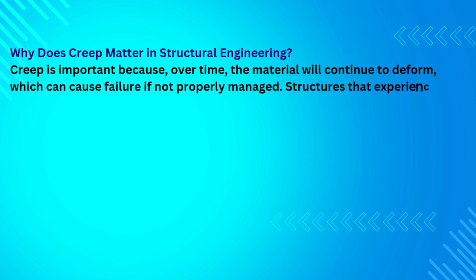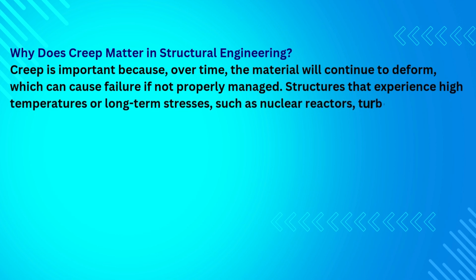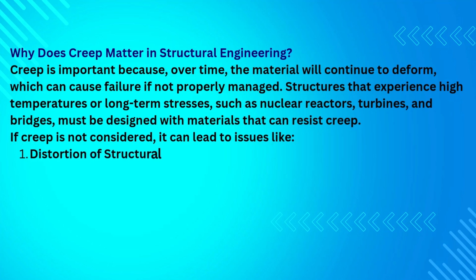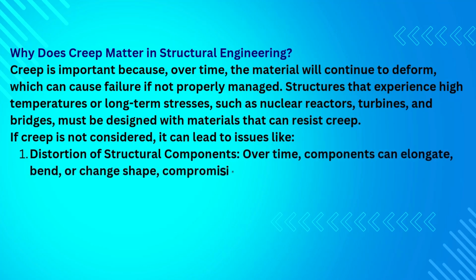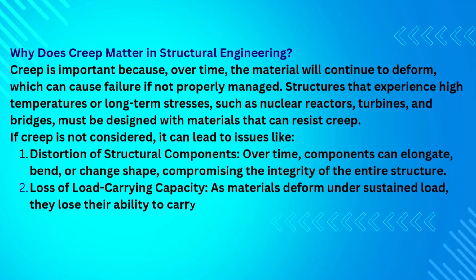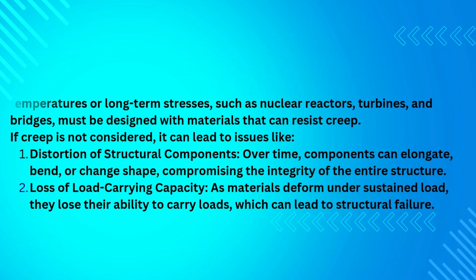Structures that experience high temperatures or long-term stresses, such as nuclear reactors, turbines, and bridges, must be designed with materials that can resist creep. If creep is not considered, it can lead to issues like: 1. Distortion of structural components. Over time, components can elongate, bend, or change shape, compromising the integrity of the entire structure. 2. Loss of load-carrying capacity. As materials deform under sustained load, they lose their ability to carry loads, which can lead to structural failure.